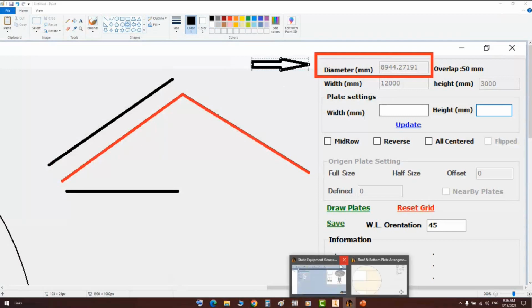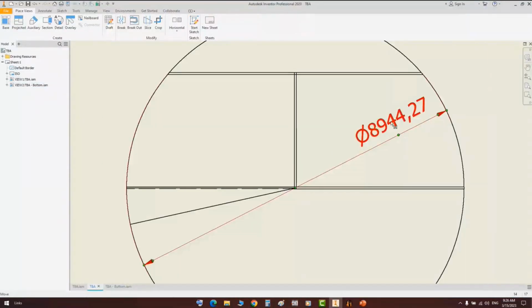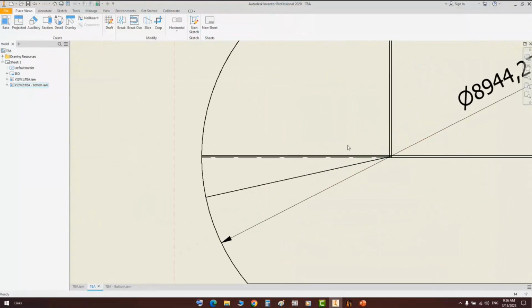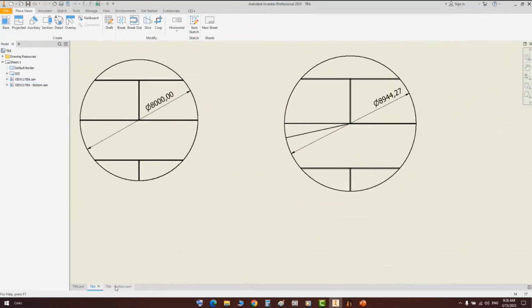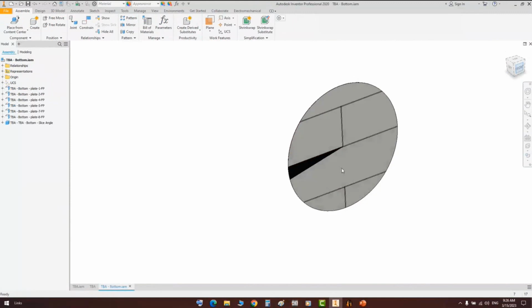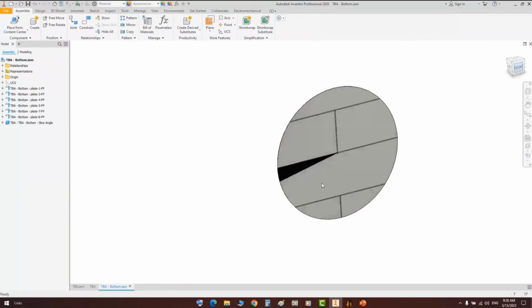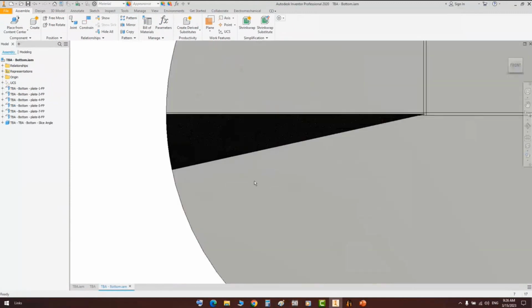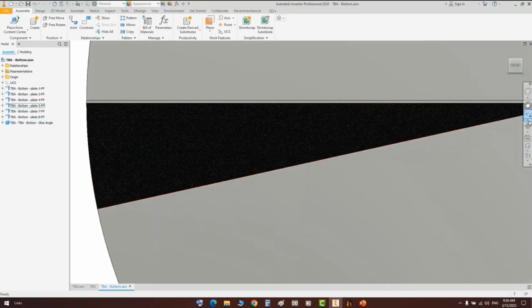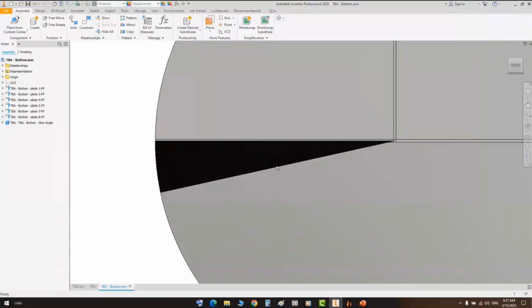So that's the actual diameter of the blade after getting the flat pattern. If we come back here to the 3D model, because you have a huge value between the slope 1 to 2, you can figure that that's the slice angle that you will need to remove to weld this edge with that edge to get the conical shape. Now, to get the conical shape, you will need to cut a slice. After that, you will need to weld that edge with that edge.